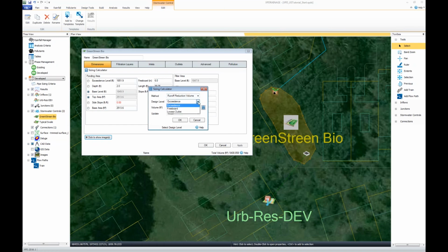design criteria. So just, hey, this whole facility needs to fill up. Okay, well, that's the exceedance level. That's the top of my facility. Often we might have the freeboard. So that would be, that kind of safety margin at the top. We need to size the facility, but you know what? You can't use the freeboard, so we could use that as a design criteria. Something I think is pretty neat.